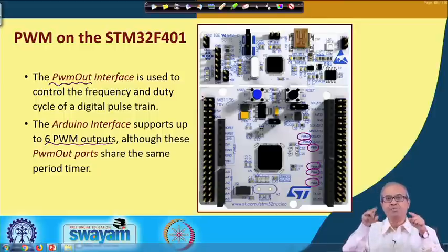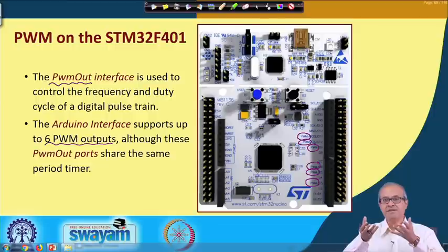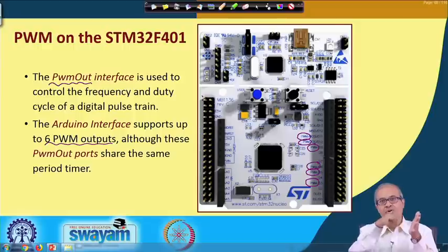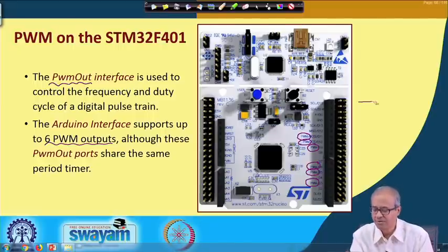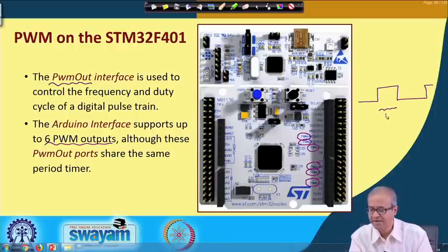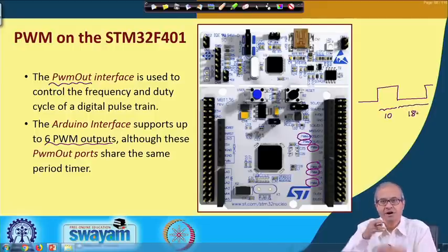Now, essentially these PWM signals on and off are generated using some timers. Well, you can put the output to 1, load the timer with a value, and with a clock the timer will be down counting, you wait till it goes 0. Like for example, this on period can represent a count value of 10 and this off period can represent a count value of 18, let us say. So, I will be loading the counter or the timer with that appropriate value and let it go on counting down till it reaches 0, and as soon as it reaches 0 I change the value of the signal,